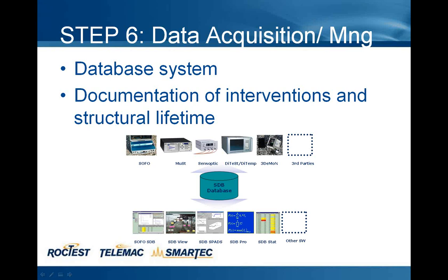Also, we have to document intervention and structural lifetime events. So document what actions have been carried out on the structure, what happened around the structure itself. All this information can also be integrated into the SDB database. So the database will also act as a kind of link between the hardware, the sensors, the data acquisition system, and on the other side, the software that is used to manage, display, and publish the data.